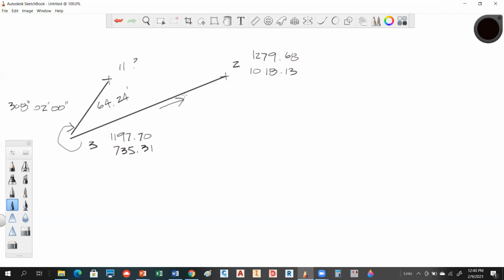Okay, so the direction of the arrow doesn't take effect until... No, okay, now I know what you're saying. This is the arrow head, this is the tail. You have to go to where the tail is. This is the line you want. The arrowhead's your foresight. The tail is your backsight.